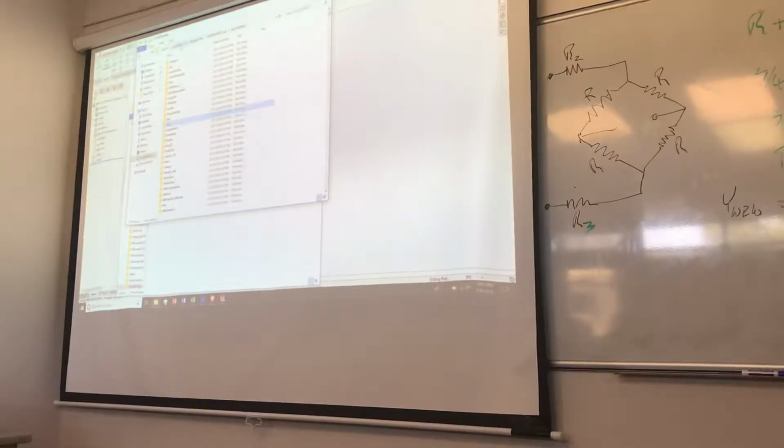Okay, so here we go all the way back out, and at my first level, local disk C, I have program data, and I've got program data for all kinds of things, and I got SolidWorks, and SolidWorks 18, and I have design library, and I have Weldments, and there's my goodie. 3 by 1.125 rectangle.